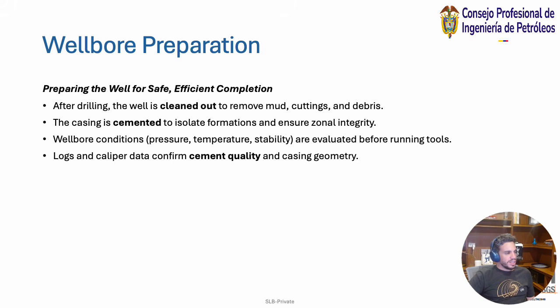The casing is cemented, and we do this to ensure zonal integrity, and basically, again, that's just our well integrity. And the wellbore conditions are evaluated before running tools, right? So this part is done in completions before you're running your logs, right? So after drilling, before logs, right? And here they do check the cement quality and the casing geometry.